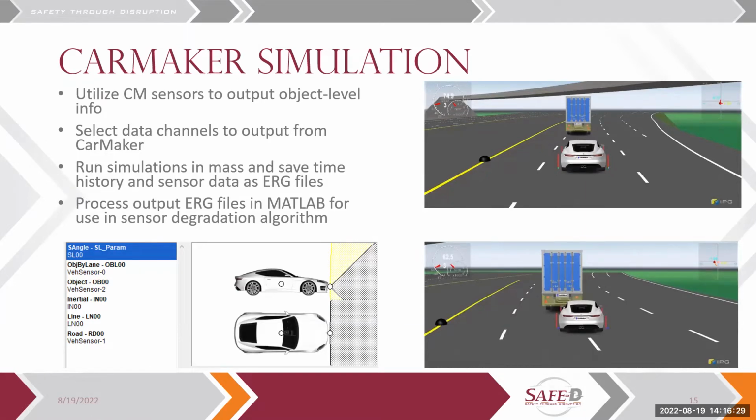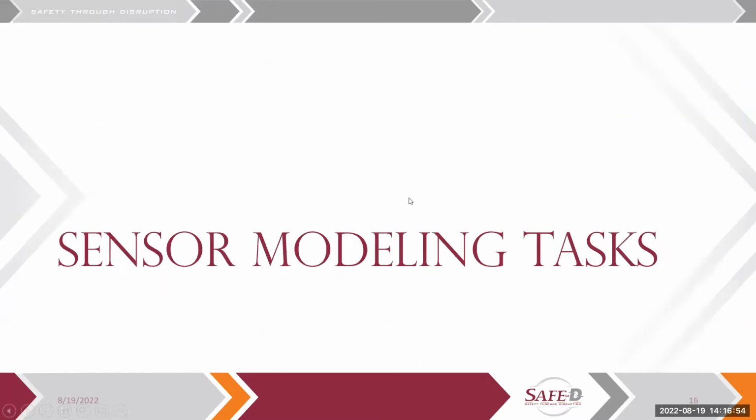And what they do is they grab the object within frame and extract that information and provide the output relative to what that sensor would see. Of course, these are just grabbing the perfect geometric response, so there won't be any real world responses there. So that leads us to the next task, sensor modeling, where we try to make the sensor data within the simulation a little bit more realistic.